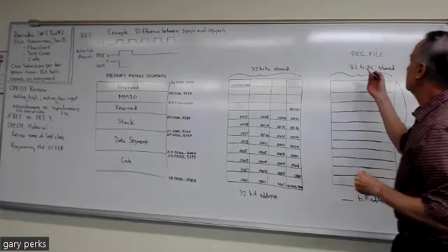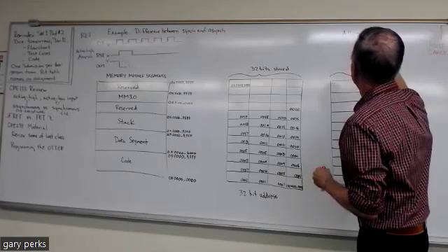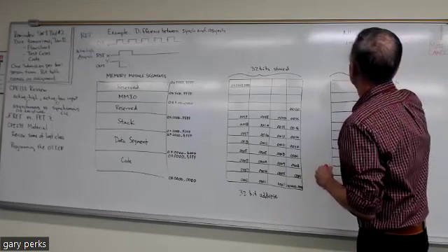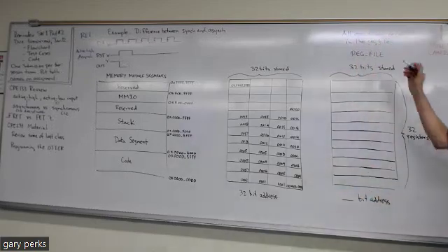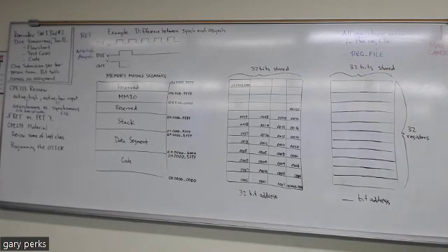All operations occur in the reg file. What I mean by that is, when you do a NOT, like for software part 2, what you're going to hand in, at least one way to do that problem is you'll have a NOT command to invert all the bits. Well, that inversion of the bits is going to happen in a register that's in the reg file.